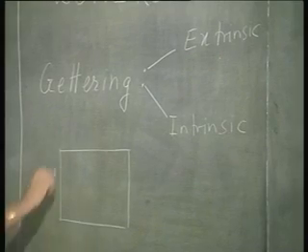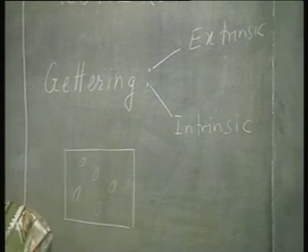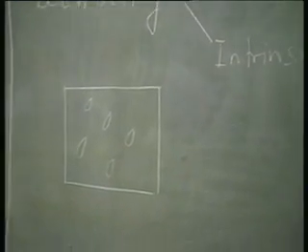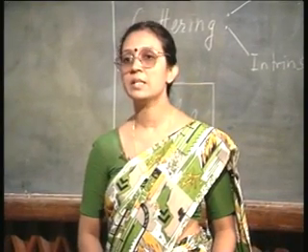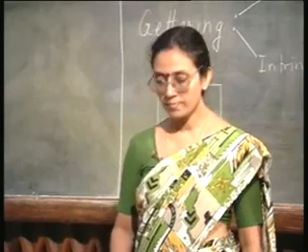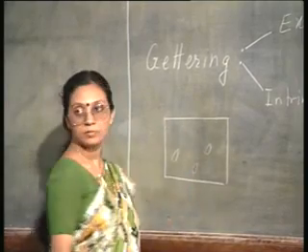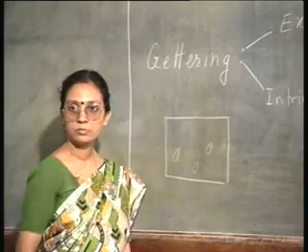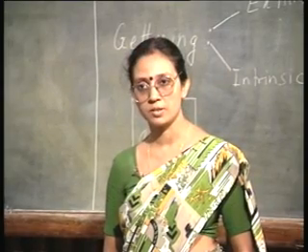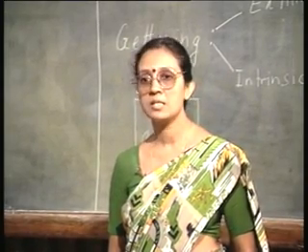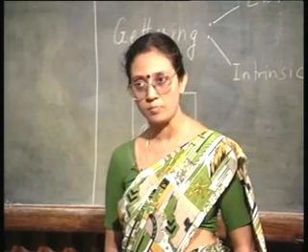This is the thickness of the wafer, full 500 micron. So, I have these oxygen precipitates all over the place. Now, I heat this wafer at 1000 degree centigrade or above in an inert ambient. What will happen? The oxygen from near the surface will evaporate out. So, the active region is free of these oxygen precipitates, but I still have oxygen precipitates deeper in the bulk, which can be used as gettering centers, which can be used as sinks for metallic impurities.